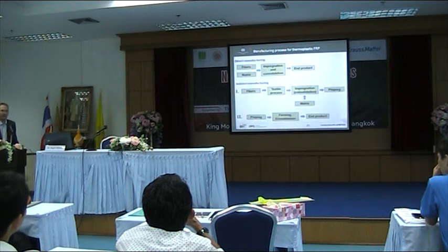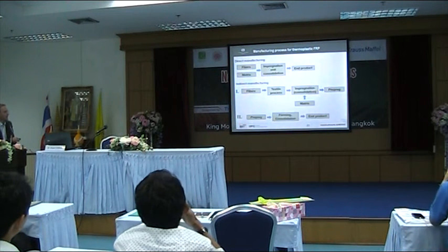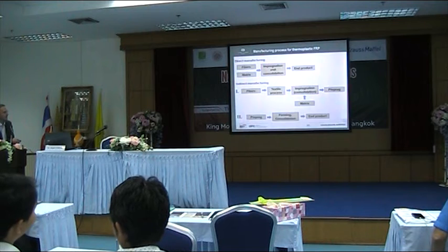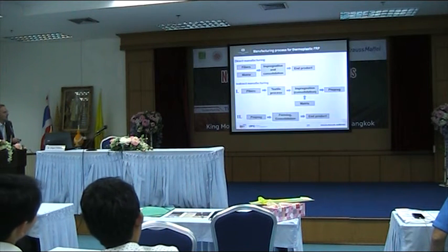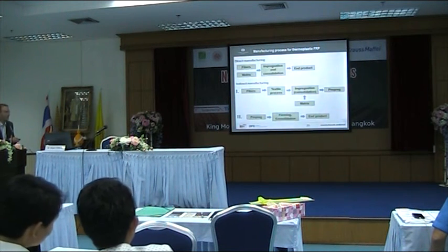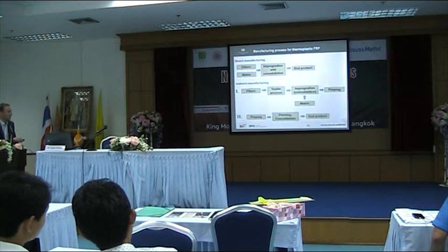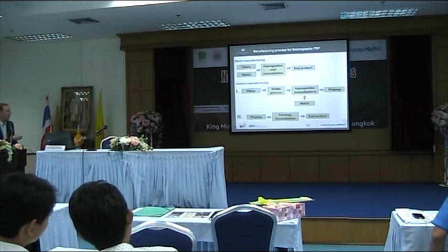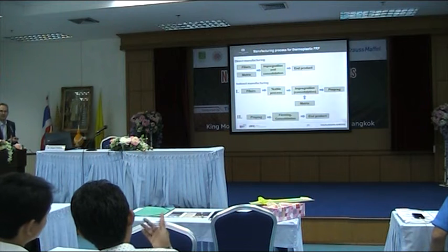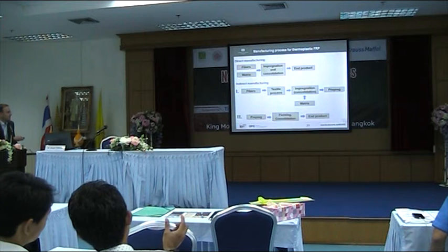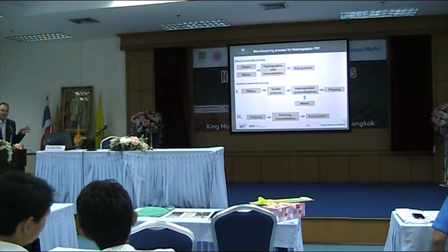You cannot feed a woven fabric into injection molding plastification units. It could be a little bit difficult. So you have so-called indirect manufacturing. You have the fibers, a fiber process, a textile process for example, and you have some impregnation with the matrix directly in the textile, and then you have a so-called pre-preg, a thermoplastic pre-impregnated material. You use it for the next step for forming and consolidation, for example, for thermoforming. So this can be separated. It must not be the same OEM. So, for example, someone buys this pre-preg and uses it for its techniques. Yeah? It can be separated.